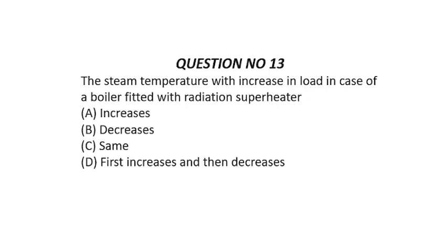Question number 13. The steam temperature will increase in load in case of a boiler fitted with radiation superheater. So what happens when load increases in a boiler? What happens to the temperature? So temperature decreases when load increases. So correct option is option B.